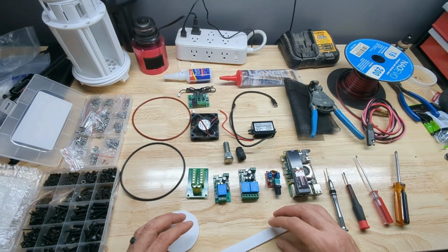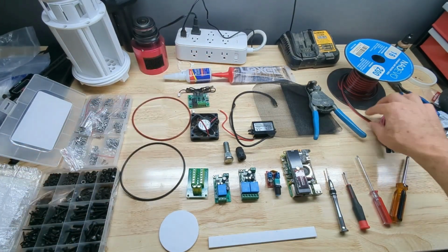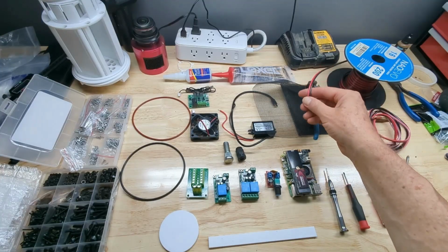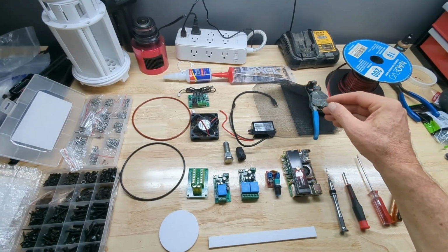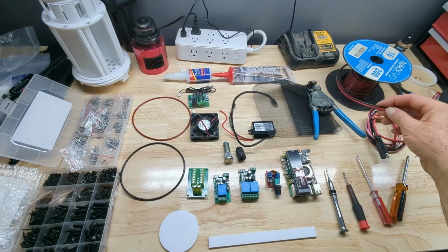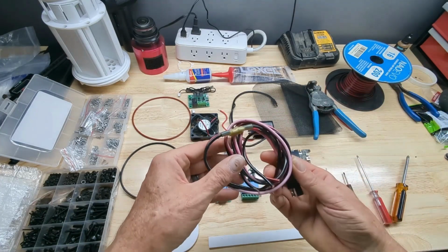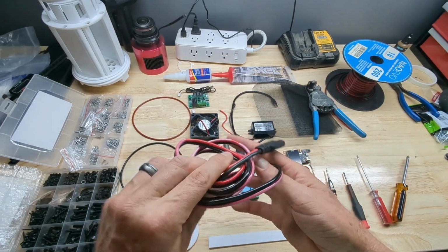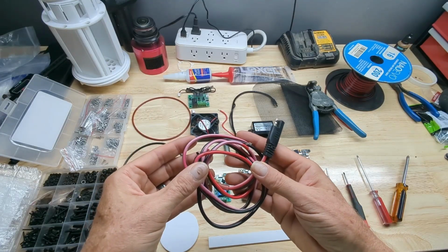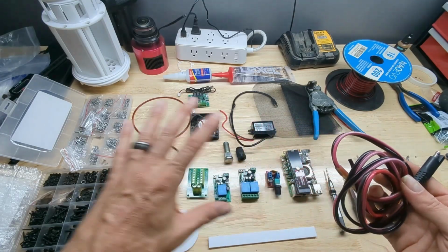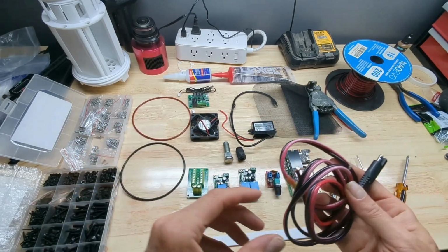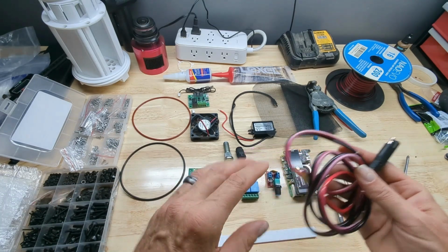Let's see, other components, the wire that we'll use. Since all the internal wiring is a very short run, 16 gauge is more than adequate. You could actually go with an 18 gauge if you wanted a thinner wire to work with. This is our power cord that we're going to use. Now, at my observatory, it's an off-grid observatory, so everything runs off 12 volts. So all the components that you see here are also 12 volts. So a 12 volt system just natively supports this.